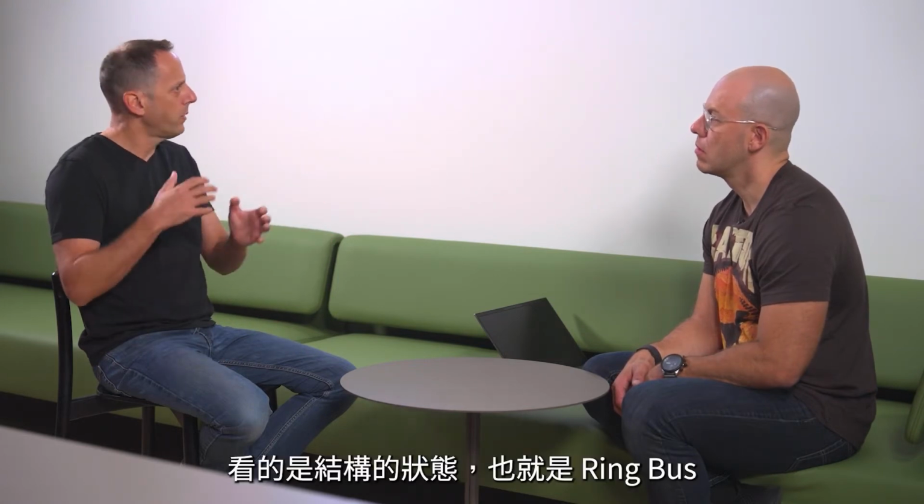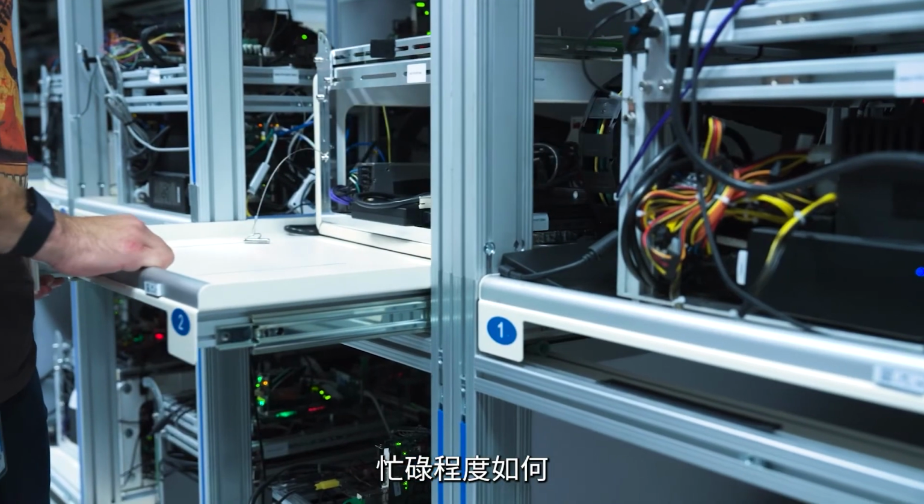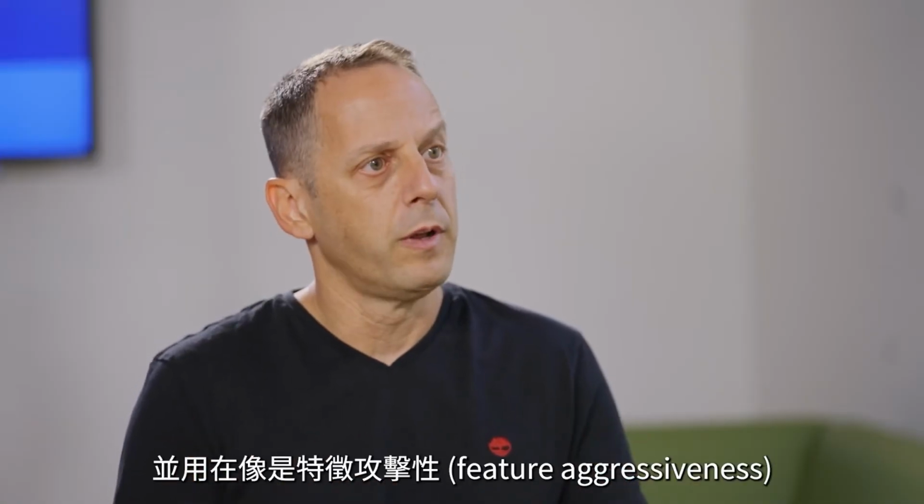In Raptor Cove, we had a new capability, a machine learning based firmware, that looks at the core behavior and dynamically optimizes and configures the core to give better performance. In the machine learning part, we are looking at the state of the core, and we are looking at the state of the fabric, the ring bus, and by that we understand the memory traffic, how busy it is, whether we have bandwidth on the ring, and use that for, for example, prefetcher aggressiveness. That's a machine learning example that we recognize.